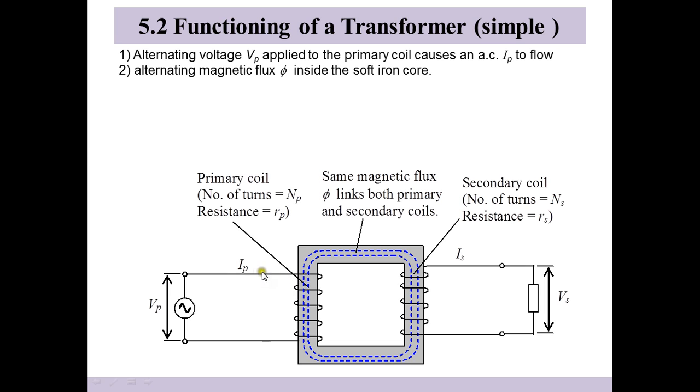If now the current is traveling in the opposite direction, that means anti-clockwise, you can see using your right hand grip rule that the B field actually points downwards. This means that as the current alternates between clockwise and anti-clockwise, we have the B field alternating between up and down on the primary side. Hence, with an alternating voltage, you have an alternating magnetic flux inside the iron coil.